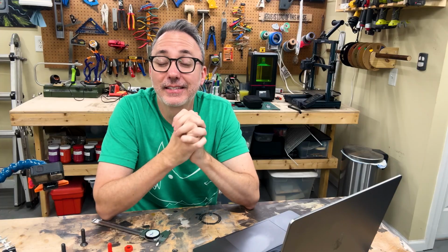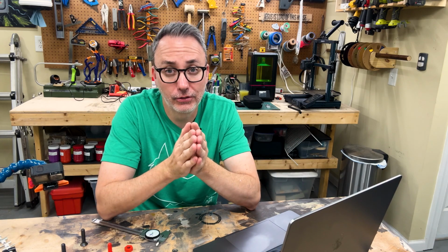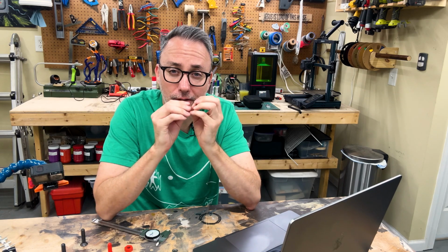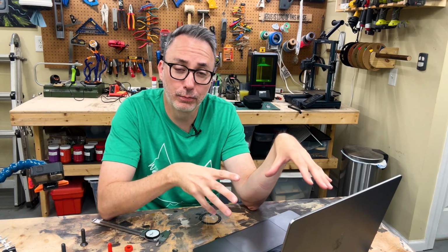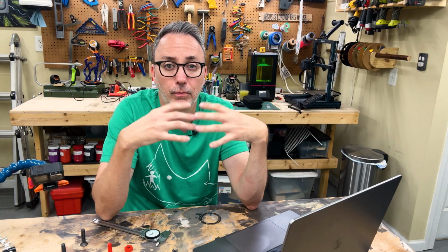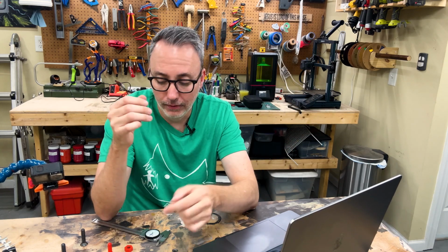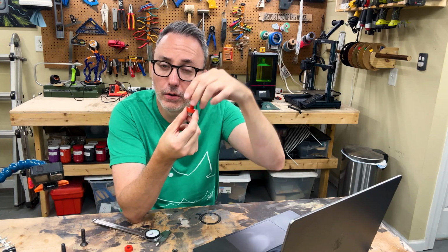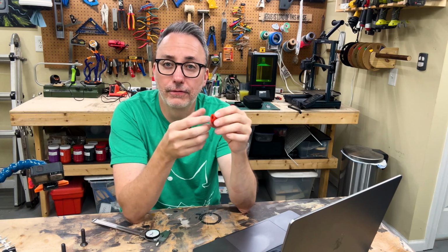that if you just wanted to 3D model and have it work, that's when you would need to use the offset. All right, so the last thing I want you to know about 3D printing threads is please, please, please, when you're setting it up in your slicer, do not use supports. It's going to be a mess. It's so intricate and so tiny that it'll just fuse to it and you'll hate yourself. So however you set this up to print, make sure that you're setting yourself up so that it's being printed in a way that you can do it without supports. So usually that's facing, so I printed this like this. And so it was able to do those overhangs because they're so small. And I printed this guy like this with the hole facing up, and yeah, it printed fine.